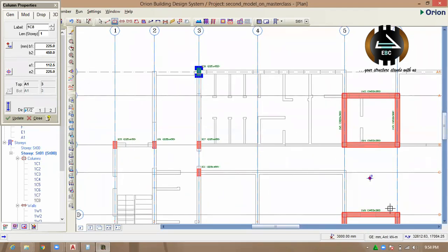Okay, what did you say? Is it advisable for the shaft to have columns at the corners? It is not advisable to have columns at the corners of a shaft. You already have a wall, as in what you're talking about is a whole wall being reinforced. It's not advisable. What's the essence? What's the work of the column?